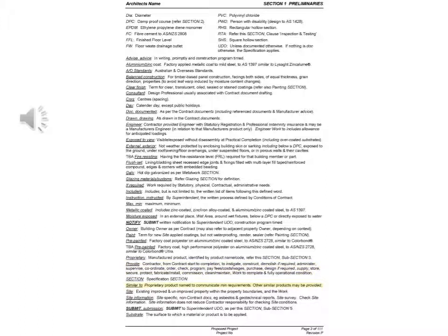Similar to is the only way a manufacturer is specified. It is used only occasionally to define quality. Used for a material made by a number of manufacturers, e.g. plasterboard, reading similar to CSR Gyprock plasterboard. Equal to is not used, as it cannot be quantified and does not allow better quality.